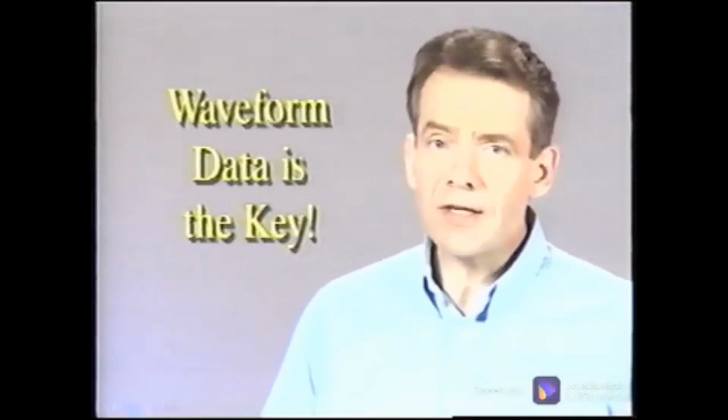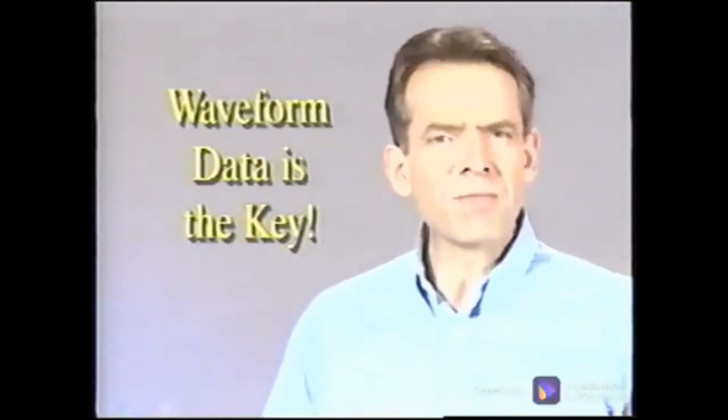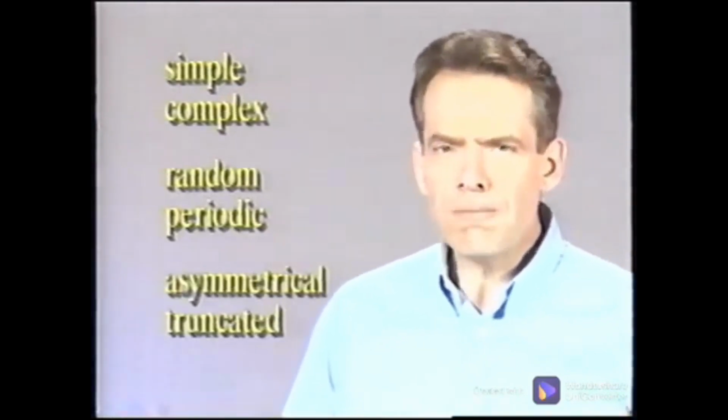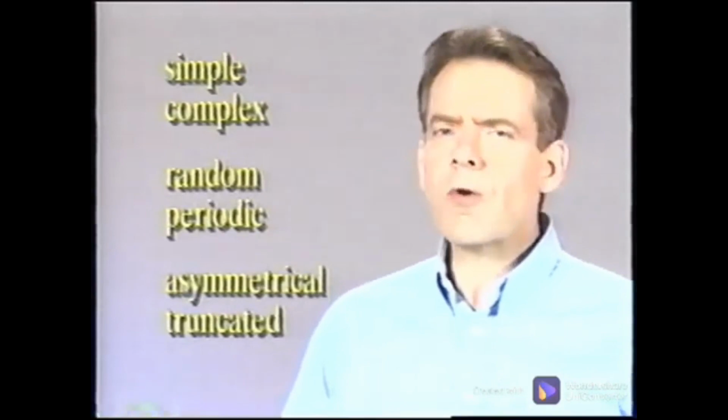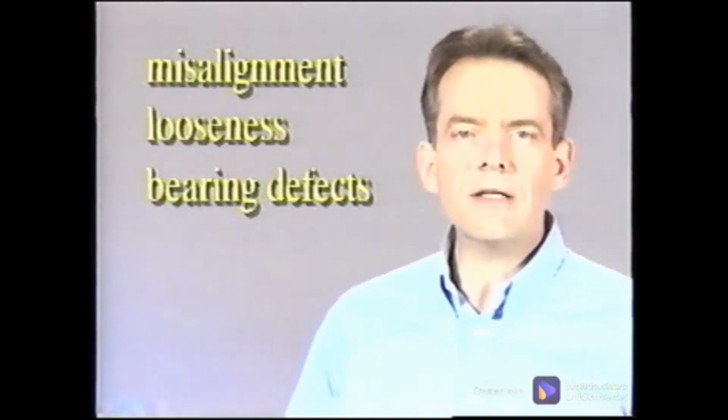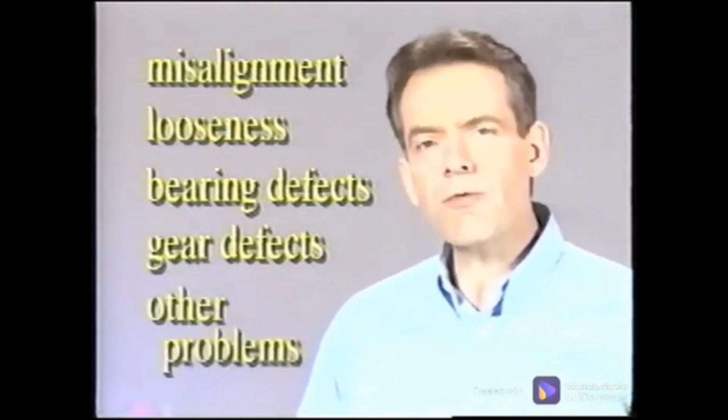Waveform data is often the key to diagnosis that might not have been evident from spectral data alone. Whether simple or complex, random or periodic, asymmetrical or truncated, waveform characteristics can truly provide helpful information, which leads to a more confident diagnosis of misalignment, looseness, rolling element bearing defects, gear defects, electrical, and other machinery problems.